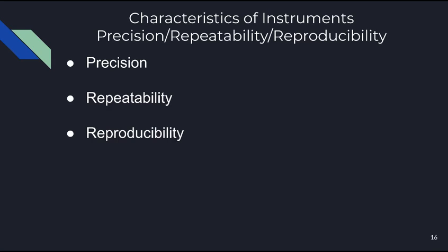Reproducibility describes the closeness of output readings for the same input when there are changes in the method of measurement, observer, measuring instrument, location, conditions of use, and time of measurement. Both terms thus describe the spread of output readings for the same input. The spread is referred to as repeatability if the measurement conditions are constant, and as reproducibility if the measurement conditions vary. The degree of repeatability or reproducibility in measurements from an instrument is an alternative way of expressing its precision.